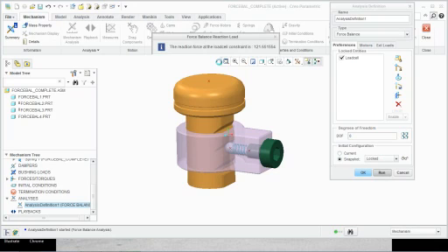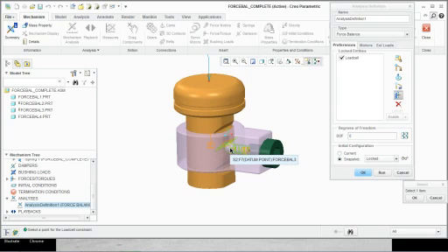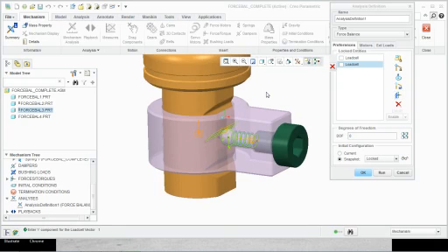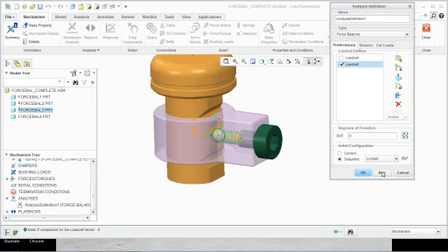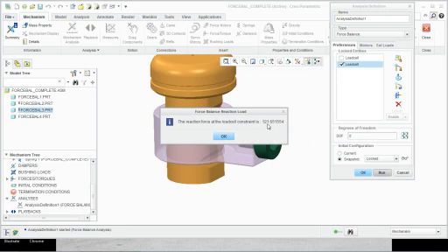So let's see how I created this load cell. I go right here, say load cell, you have to select a point, then you have to select the body, and set the load cell direction. See, this is the Y direction, so it's not acting in X. In Y it is 1 and Z it is 0. So you can see that's where the load cell is. When you run, it's going to tell you how much reaction force is needed in the Y direction.